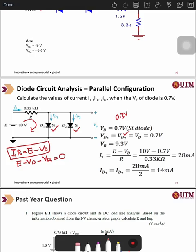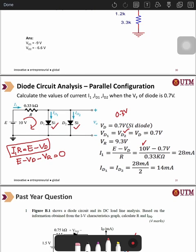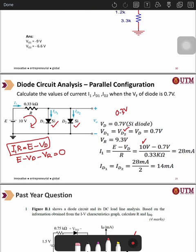Your E is 10 volt, and your VD is 0.7 because it is connected in parallel. Again, your R is 0.33 kilo ohm. Now you can get I1 equal to 28 milliampere.